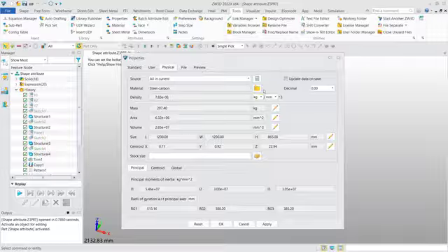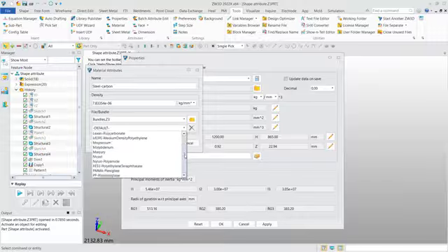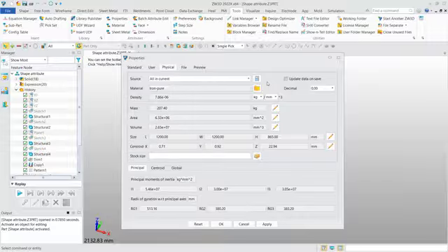First, we click File icon. Then we can select the material inside ZW3D, and click OK. Then we can calculate the mass property. And if you want more materials, you can add it by yourself. Here I will show you two ways to add.